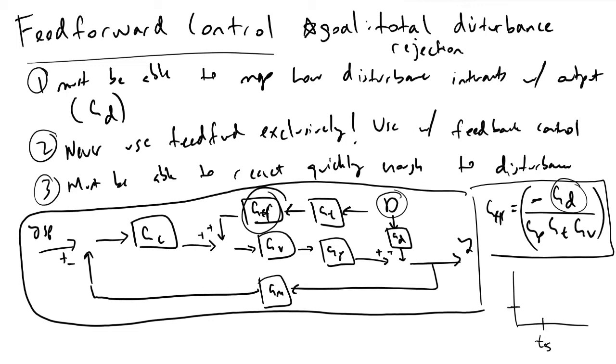What we would find if we could respond fast enough to it and we had a good enough model is that nothing would happen to our set point, so our set point temperature, for instance. And so this is the ideal. And so this is what we want with feed-forward control, and we do the best we can to get there. And this kind of wraps up the why we care about feed-forward control and the math behind it, as well as the control block diagrams.